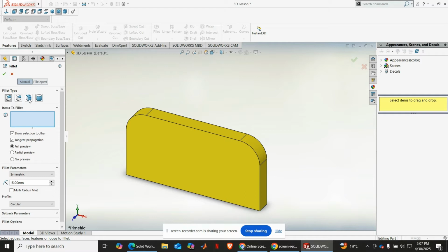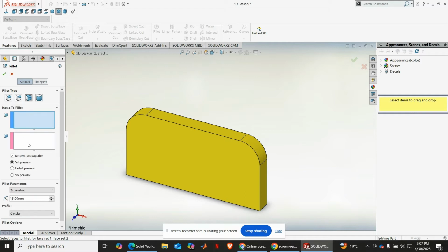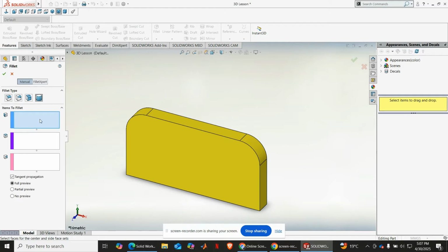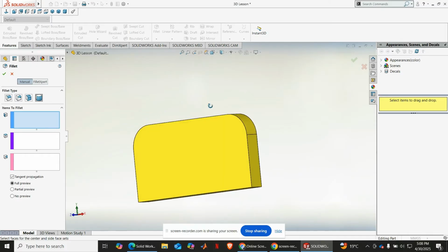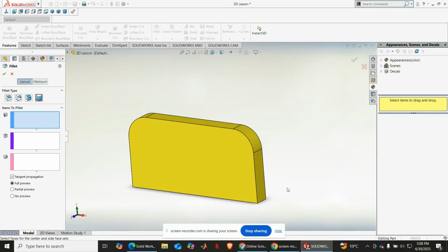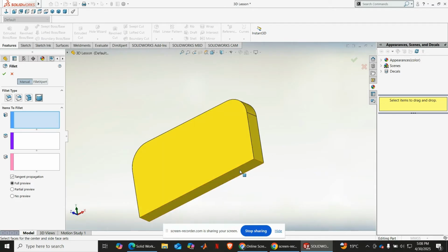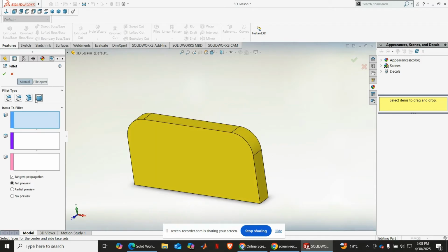Okay, so you can choose this one and say items to fillets, or this one select three faces, 1 2 3, like let's say 1 2, lower 1 3, like this is face 1, this is face 2, this is face 3, then it will put a fully defined curved fillet like that. I mean, you will explore that, right?